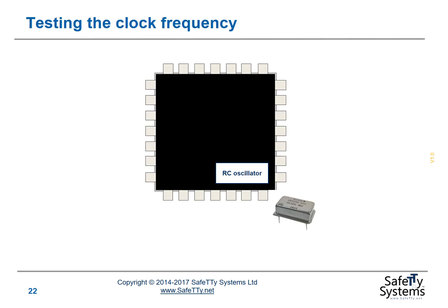The typical way that we test the clock frequency in a single processor design is that we base the design on some form of external crystal oscillator, and we use an internal RC oscillator or similar on the microcontroller as a simple benchmark to check that the external oscillator is operating at roughly the right frequency.